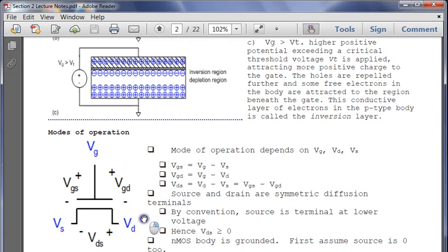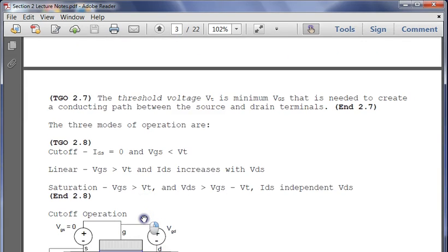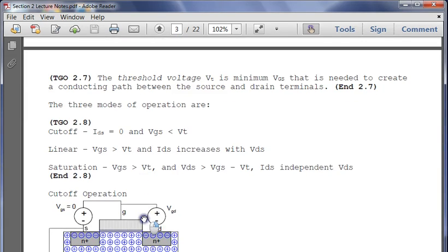So what we're having here is we've got to apply some sort of threshold voltage with PMOS. And you can tell it's low because we're applying a 0 to get a 1 through, right? So again, we're going to have this different gate drain, and now we're going to have the 1 come through. That's the objective. So we'd formally define the threshold voltage, VT, as the minimum gate source voltage that is needed to create a conducting path between the source and drain terminals.